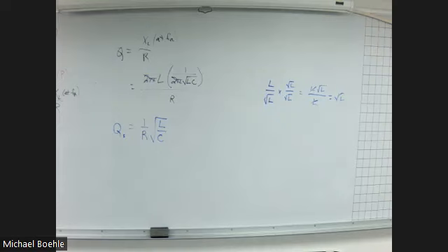Components. Okay. Well, the resistor is a resistor. But what other component has internal resistance? You've already had to deal with it. Supply. Okay, the supply does, but not that supply. This, right? The function generator. All right. See the label on there. What's it say? 100 ohms. If you have a box on there, that adds 50 to the other 50 that's already there. So you still have 100. What else has resistance?